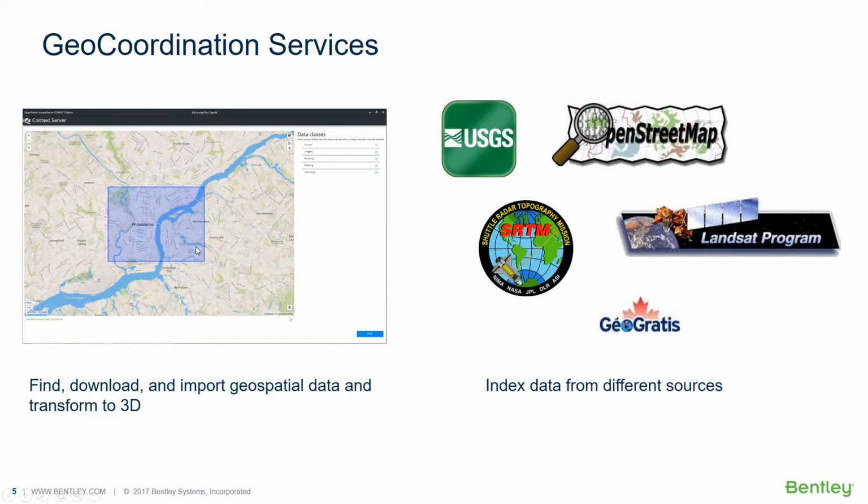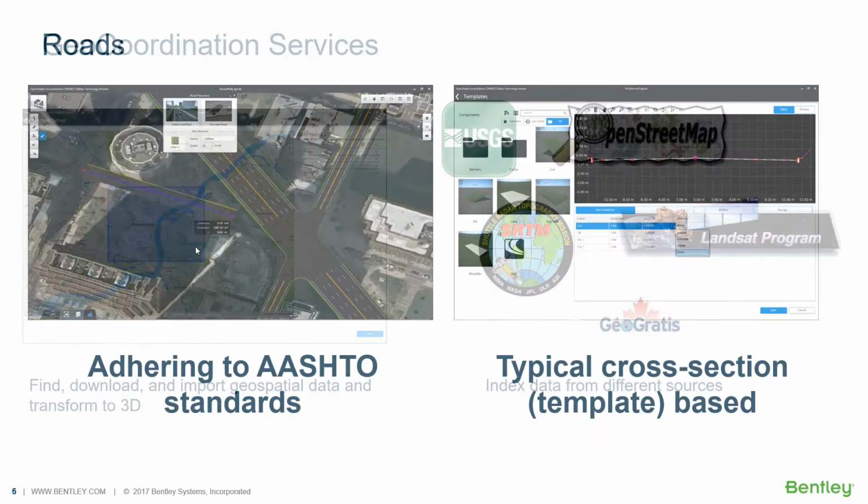You do want to set it up so that you have your projection correct from the beginning. It saves time at the end when you go back out to design if you set up your projection to be the projection that your designers are going to work in too. And USGS now has some alternate sites to pull data, and there's some very, very fine data available to pull down if you don't have your data locally collected.